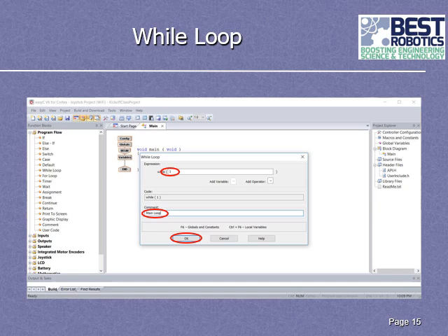When you drop the function onto the programming field here, a pop-up will come up. Now this will be the same for all the functions you drag over and drop. Some sort of a pop-up will come up. Each one will obviously be different because it'll require different data. But here you want to tell the while loop to basically run forever.